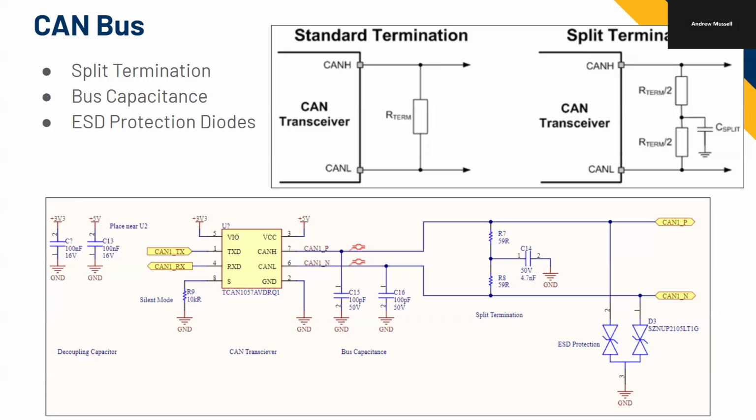Alex, want to talk about the ESD really quick again? Yeah, so these are basically the ESD symbol that I'm showing on the bottom right over there. The package that I have is two ESD diodes in one integrated circuit package. And it's basically two diodes whose points face each other. And these are Zener diodes. So like diodes, right? We think they only conduct current in one direction.